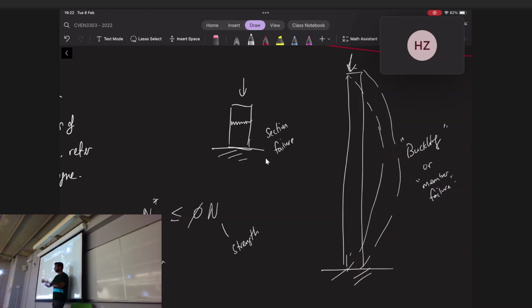So if you're going to use a steel column, what is this number? If you're going to use a concrete column, what is this number? Timber, what is this number, right? So this number changes depending on what you're using. And the only way to figure it out is you're doing a study on the material itself. Okay, so this thing here that we talked about is a study of the material. We are saying, oh, at 150 kilonewtons, it'll fail through buckling.